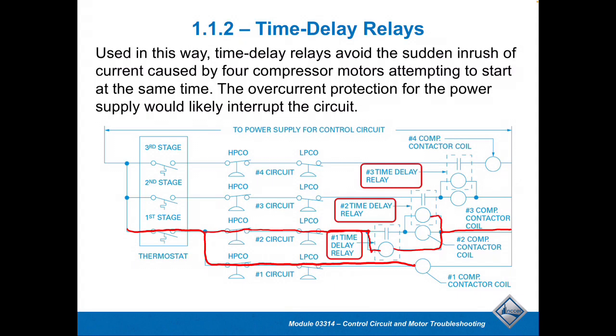Now what we're going to do is wait for a certain amount of time. Whatever that time happens to be, maybe 30 seconds, maybe 5 minutes, it really depends on how they want the system to be structured. If the only intent is to minimize an inrush, you could easily put a 10-second or a 30-second delay to prevent any type of problem, because a compressor should start within a few seconds for sure and be up to speed. So that's one operation.